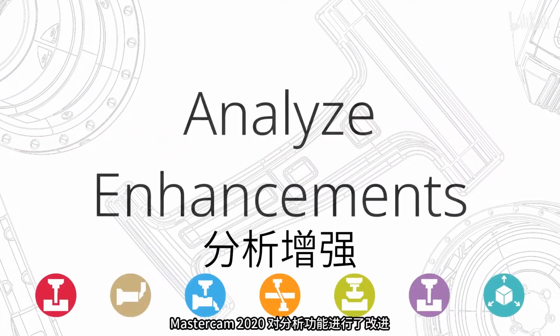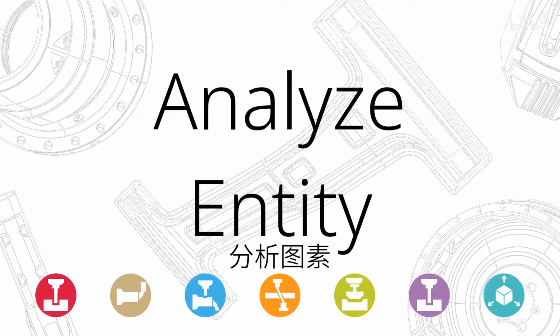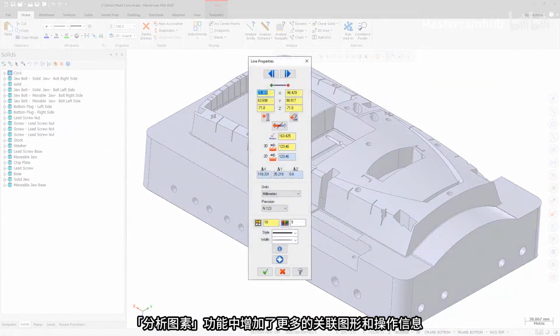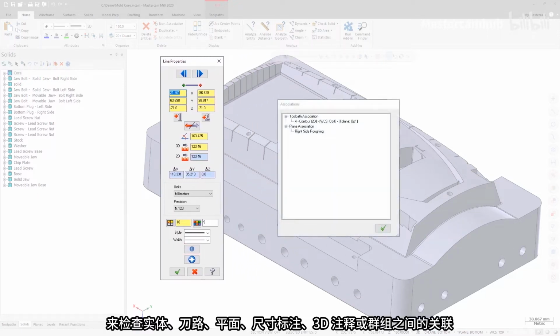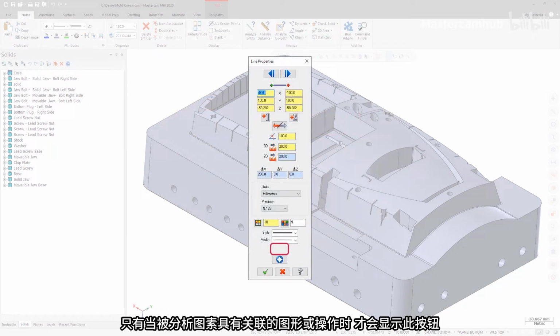Mastercam 2020 includes a number of enhancements to analyze functions. Analyze Entity now includes additional information about associated geometry and operations. Click Association in the Analyze Properties dialog box to check for association to a solid, toolpath, plane, dimension, 3D annotation, or group. This button displays only if the Analyze entity has associated geometry or operations.